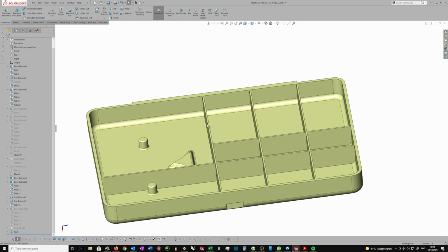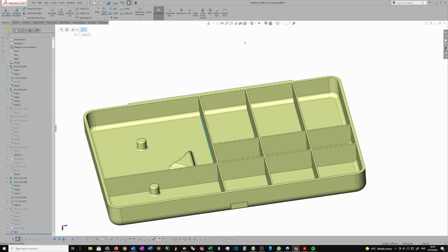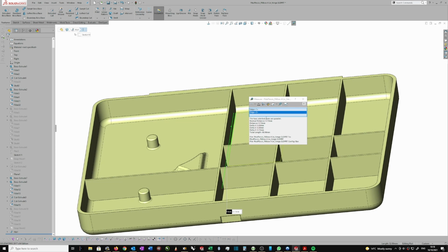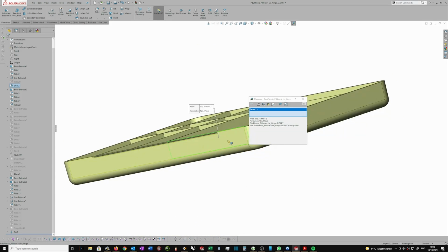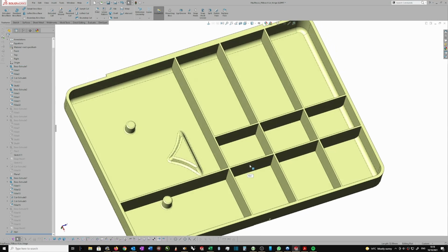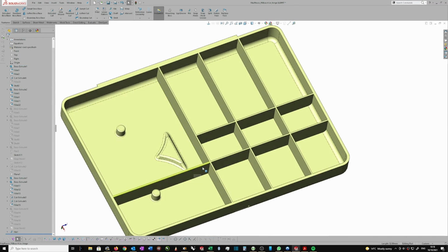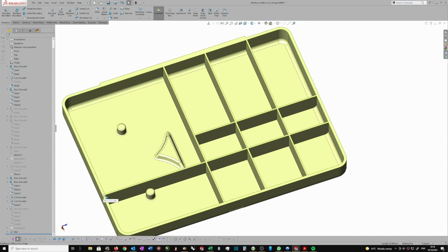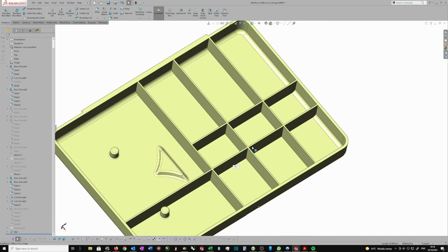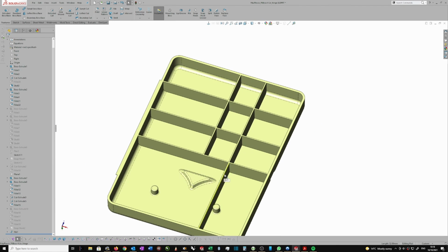They've got their tapers in. If I measure them, I'll find that distance there is 0.72. There we go, 0.72. And if I measure my wall thickness, let's just get rid of both of these, between there and there, that's 1.2. So perfect. That's exactly what I want. So look at what happened with this line that I sketched just to a certain point. It'll continue till it meets another wall. So that's the way that you stop your ribs going beyond the point that you don't want them. You just make sure that you don't draw them beyond the point of the other one.